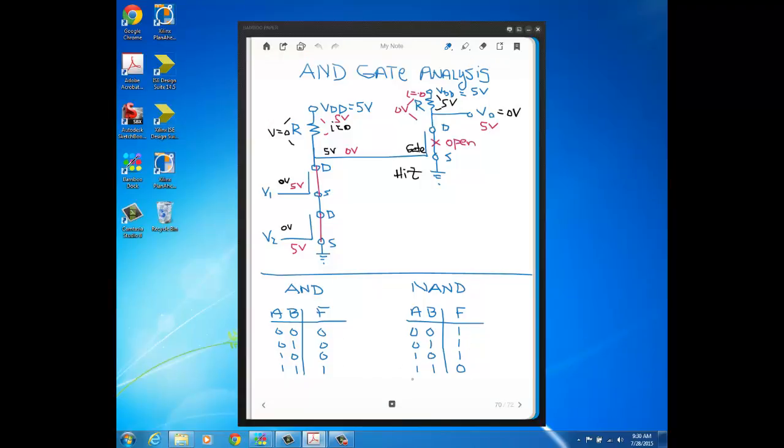So again, a NAND gate is the same as taking an AND and putting an inverter on the output, where here the inputs are A and B, and the output is F. So the logic symbol of a NAND, with the little bubble on the output, is to signify that there's an inverter on the output, that the NAND is an AND with an inverter on the output. See, that bubble is this bubble here.